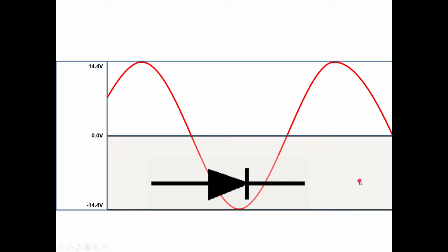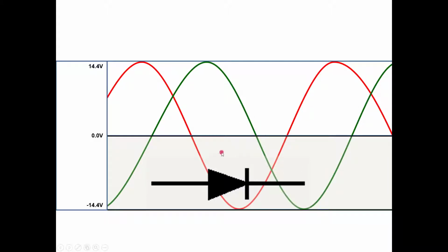So if I were to mount a second phase, being the green one, by the time the first phase were to drop, the second phase would come back on to help fill in the gap. Well, the only thing missing now would be a third phase. With 3 phases, being the yellow one being the third phase, I'm able to continue a nice steady DC current. I'm establishing that DC current.